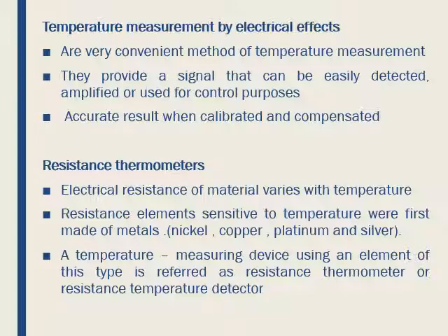When measuring temperatures above the boiling point of mercury, that is 390 degrees Celsius at atmospheric pressure, mercury may evaporate and condense in the top of the stem. This is prevented by filling the space above the mercury with nitrogen or carbon dioxide under high pressure. This raises the boiling point and allows temperatures up to 600 degrees Celsius to be measured.